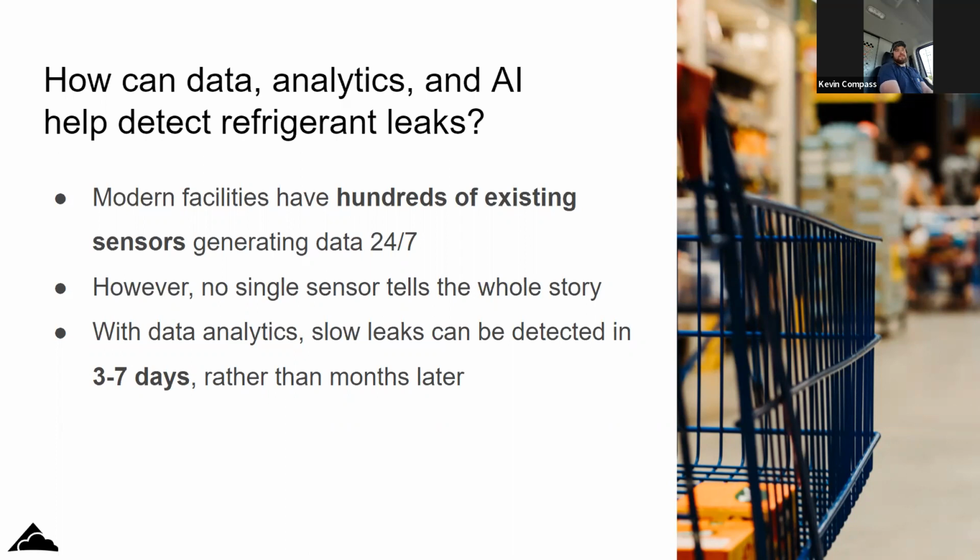That side of it would be extremely helpful for guys to actually see that data trended over time. I think it would help prevent a lot of overcharging and a lot of guys undercharging. It would prevent a lot of calls and a lot of leaks before they happen.